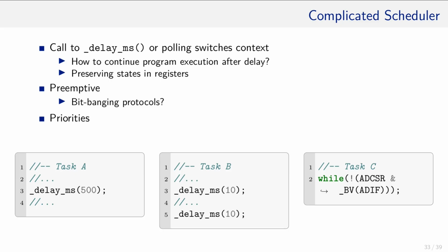For instance, the AVR library supplies a function to introduce delays, and we used them many times in previous exercises. Recall how delay_ms is implemented. Based on the preprocessor macro F_CPU, the library computes how many times a loop has to iterate to get the desired waiting time.